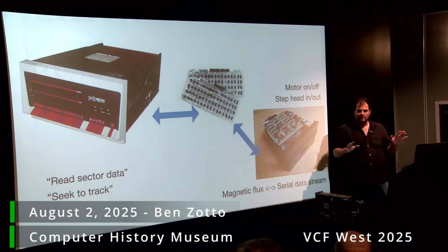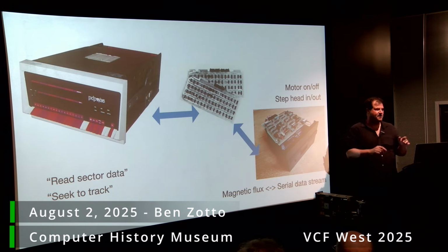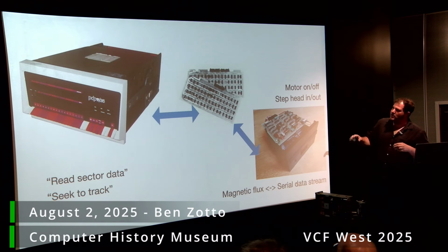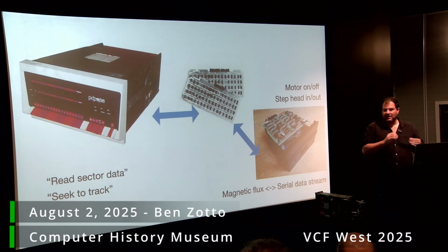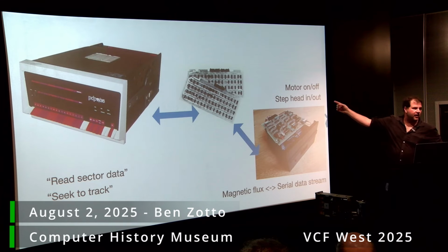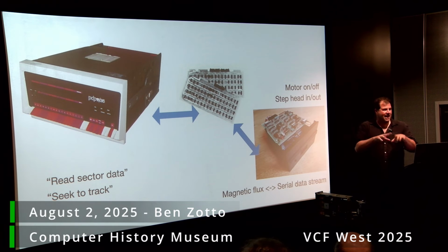They're kind of these high-level abstraction commands of how to work with a disk. I mean, they're not super high level, right? But they're high-ish level. And then there's a bunch of electronics called the disk controller that translates that into these low-level ideas like turn the motor on and off, step the head in, step the head out, and translate all the magnetic flux on the disk into a serial data stream.